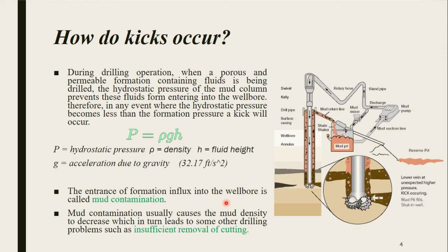Alright, let's talk about the occurrence of kicks more specifically on this slide, and let's talk about it on this figure. When we are drilling through a formation that is porous, permeable, and fluid bearing, the hydrostatic pressure of the mud column will try to restrain those fluids from entering the wellbore.